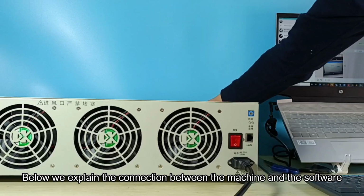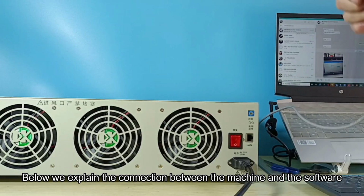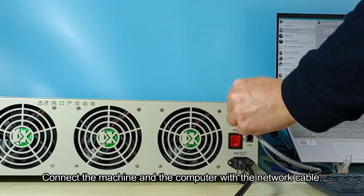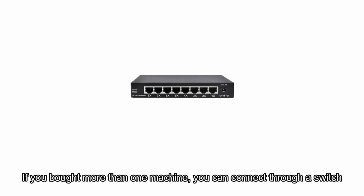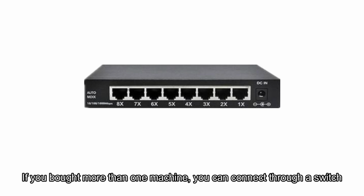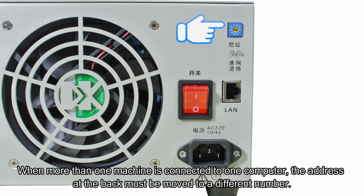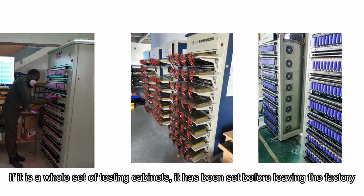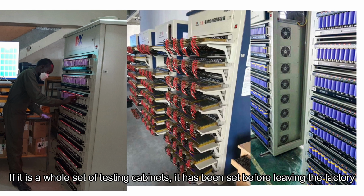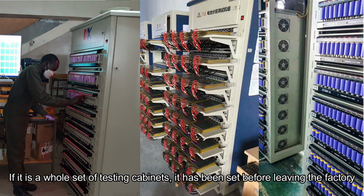Below we explain the connection between the machine and the software. Connect the machine and the computer with the network cable. If you bought more than one machine, you can connect through a switch. When more than one machine is connected to one computer, the address at the back must be moved to a different number. If it is a whole set of testing cabinets, it has been set before leaving the factory.